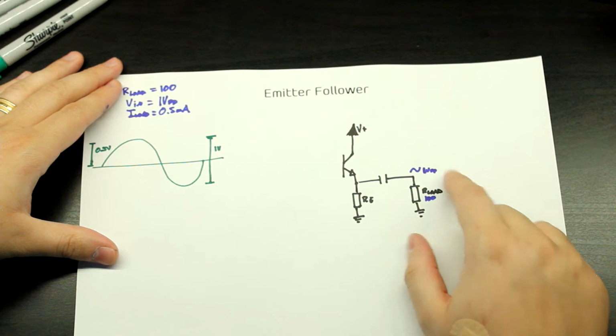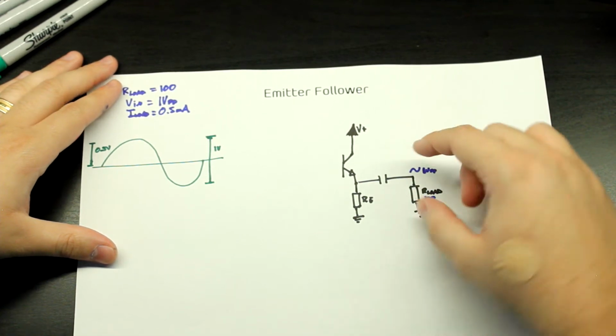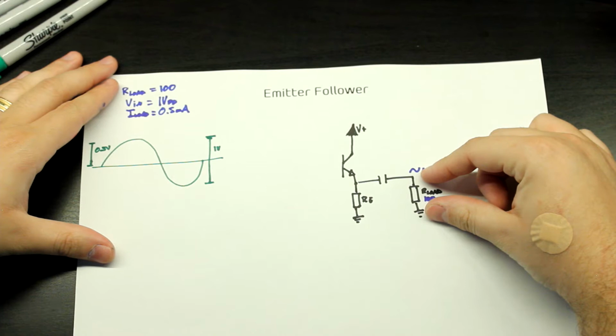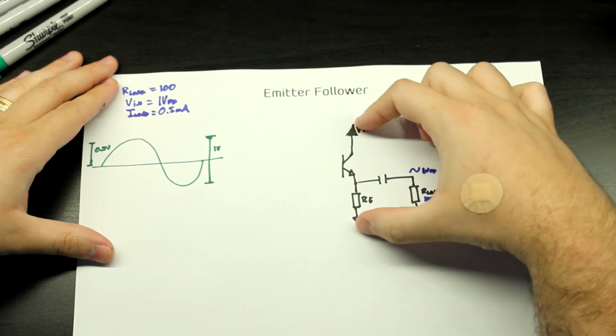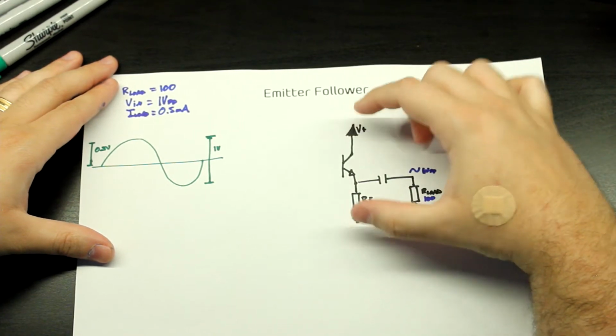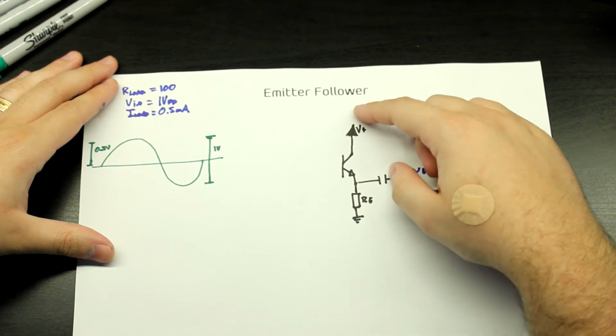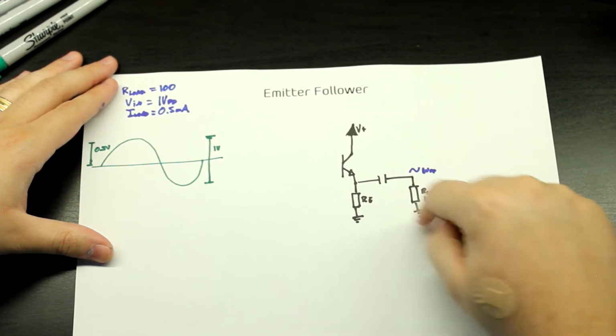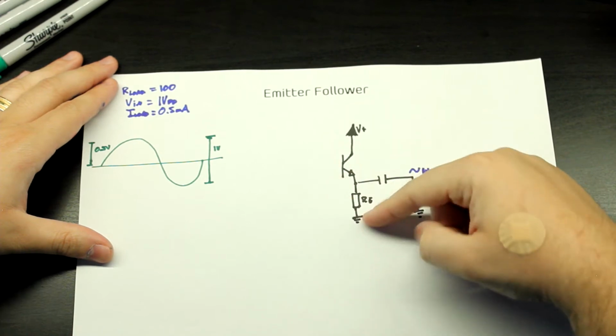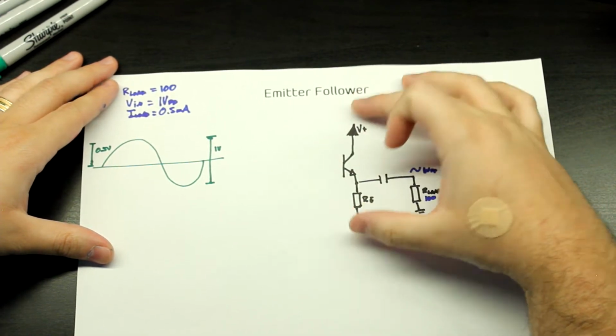That means that the rule of thumb is that whatever your output current has to be, you always need to have double the current here. So in Class A, you usually have 2 times the output current going through this, which is basically going to be a current source.